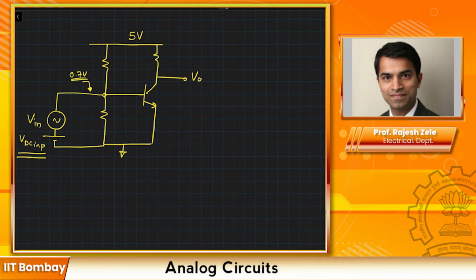In reality, we don't do it this way. Specifically, if you're looking at audio frequency signals where you're not worried about passing DC through your circuit, then we use a capacitor. This will be a big capacitor put in there, so this would be C big. If you use C big, then you don't have to have the DC input source here. So C big will isolate the DC between the two circuits.